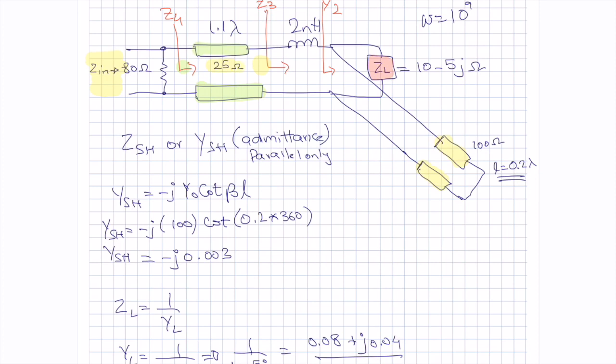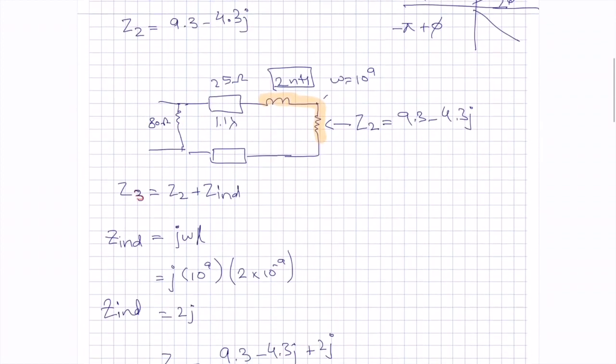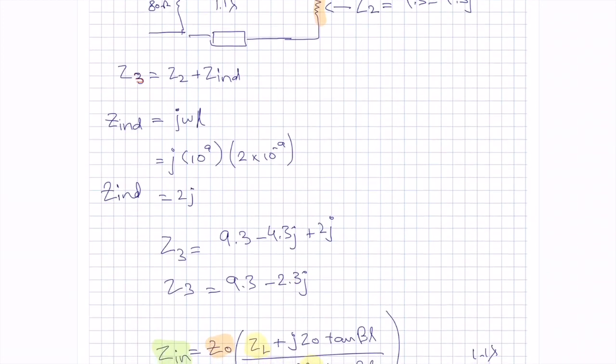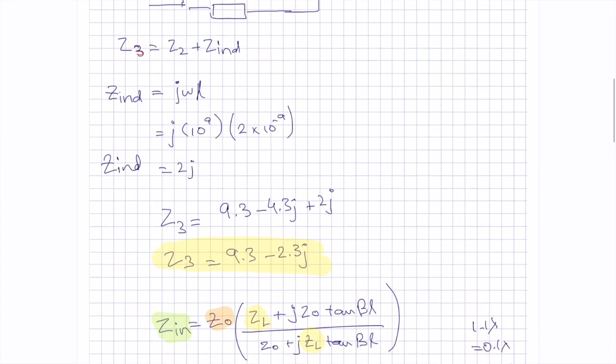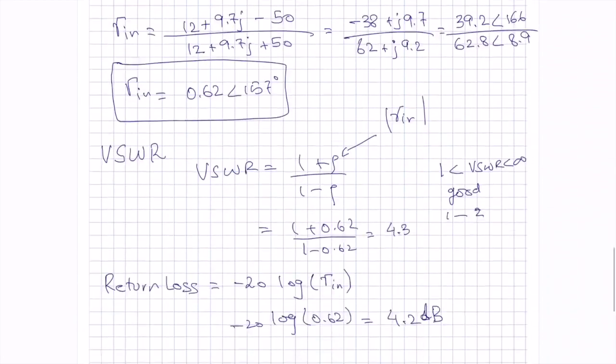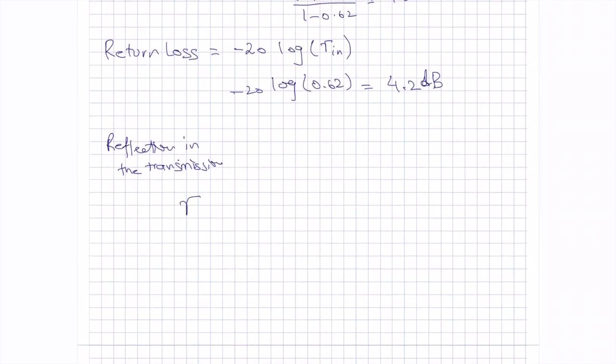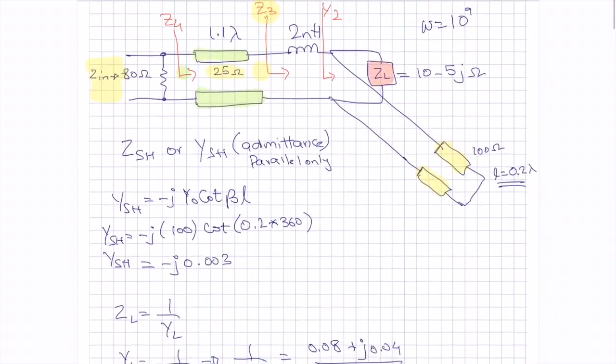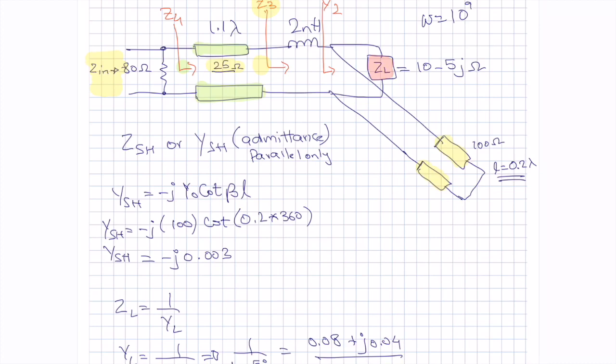As you can see, the impedance over here is 25, and the impedance to the right of this spot is Z3. Let's find out what our Z3 was. Our Z3 is this number. So let's do those numbers together. I should mark this gamma in as gamma in of the line, so that we know it's just for that line, Z3 minus Z naught over Z3 plus Z naught. If you look into this, over here in this question, it's given to be 25 ohm. Let me go back. Yes, as I already mentioned, it's given to be 25 over here.